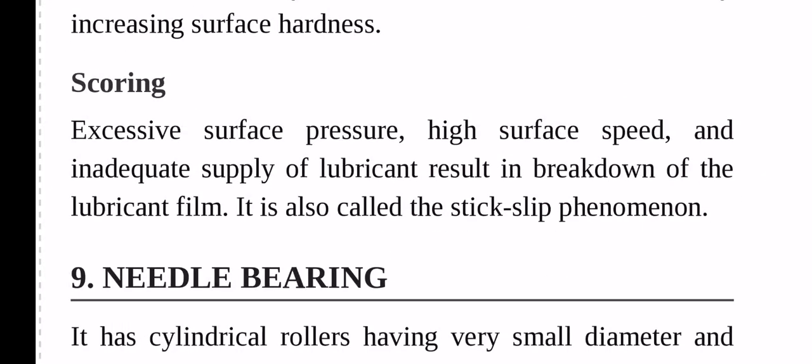Scoring: excessive surface pressure, high surface speed, and inadequate supply of lubricant result in breakdown of the lubricant film. It is also called the stick-slip phenomenon.